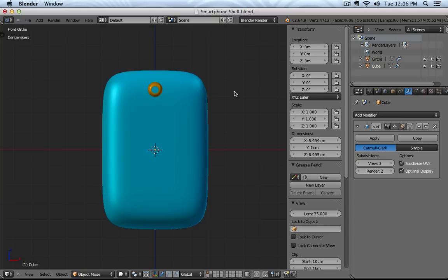At the same time, for example, let's say you build an object in Alias and then a certain shape is very difficult to build. You can export that polygon or that NURBS model from Alias as a polygon model into Blender, use it as a 3D backdrop, sculpt the part or the shell that's difficult to make in Alias in Blender, and then through Maya bring that shape back into Alias as a NURBS surface. And for that, of course, the position and scale of your 3D models is very important.